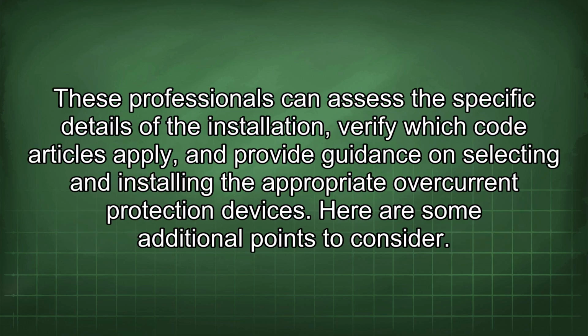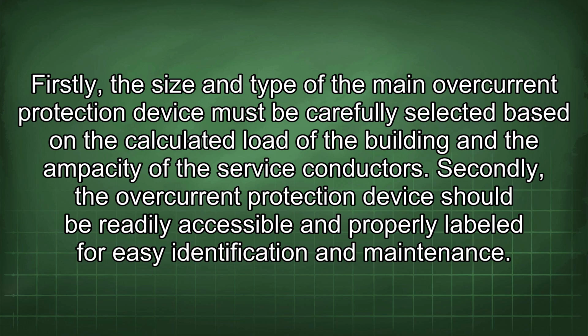These professionals can assess the specific details of the installation, verify which code articles apply, and provide guidance on selecting and installing the appropriate overcurrent protection devices. Here are some additional points to consider. Firstly, the size and type of the main overcurrent protection device must be carefully selected based on the calculated load